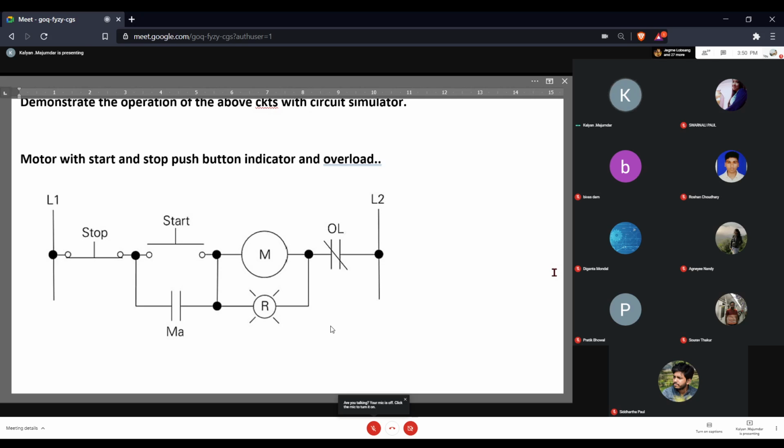The start switch. Meaning the motor starting again on its own, that is ruled out in this kind of configuration. That is the reason why this kind of configuration is always preferred rather than two-state switch or latch switches for starting and stopping a motor.